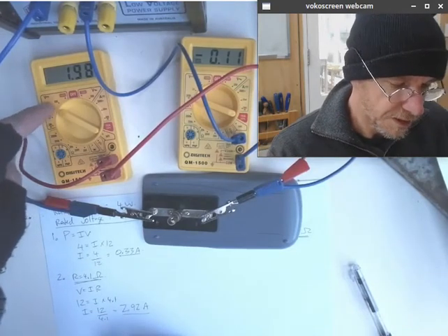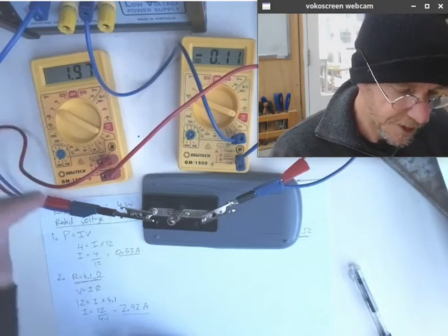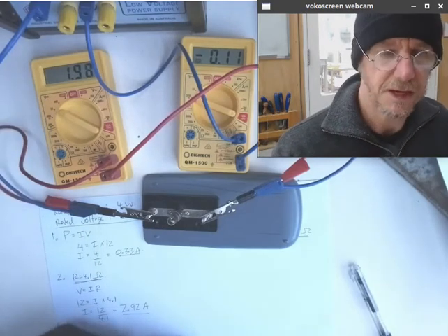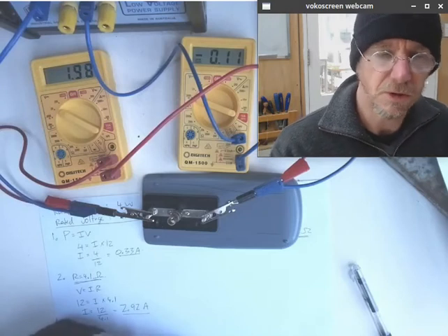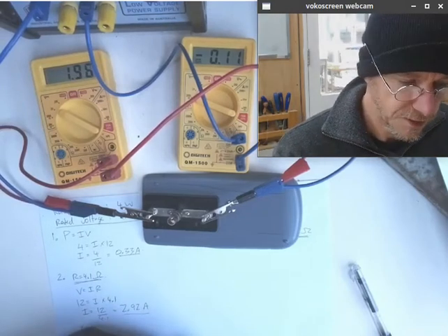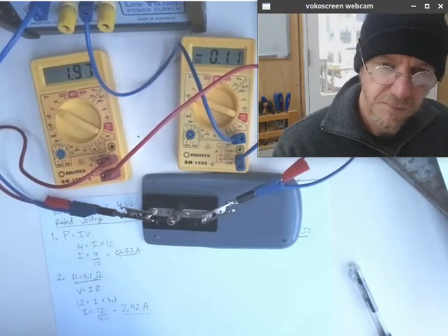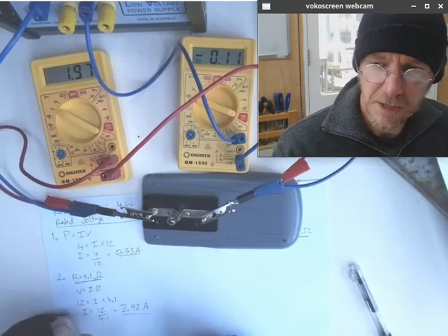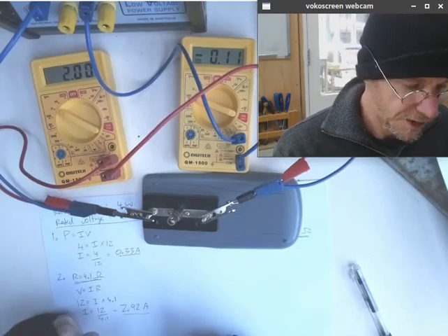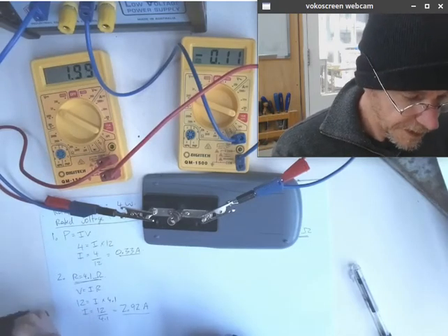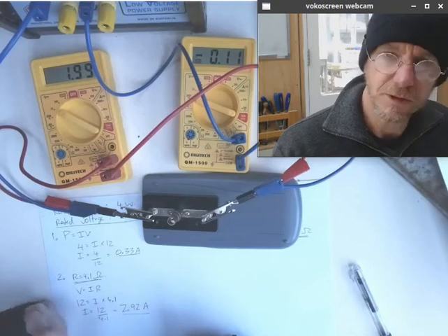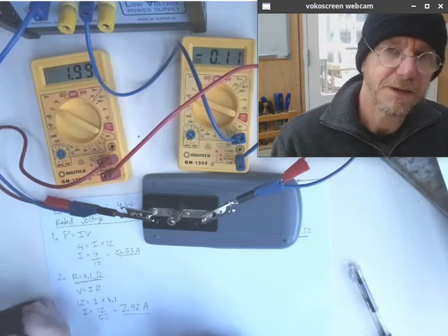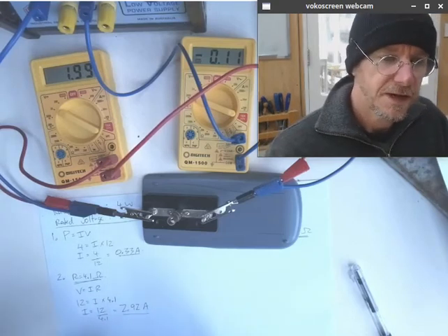Because any product that's got a heating effect, for example, and these are often products that have a high current draw or are some of the biggest power users in our house. So heating elements: the heating element heats up, and that means that its resistance changes quite substantially as it heats up. Similarly, other objects like electric motors don't behave in accordance with Ohm's law.